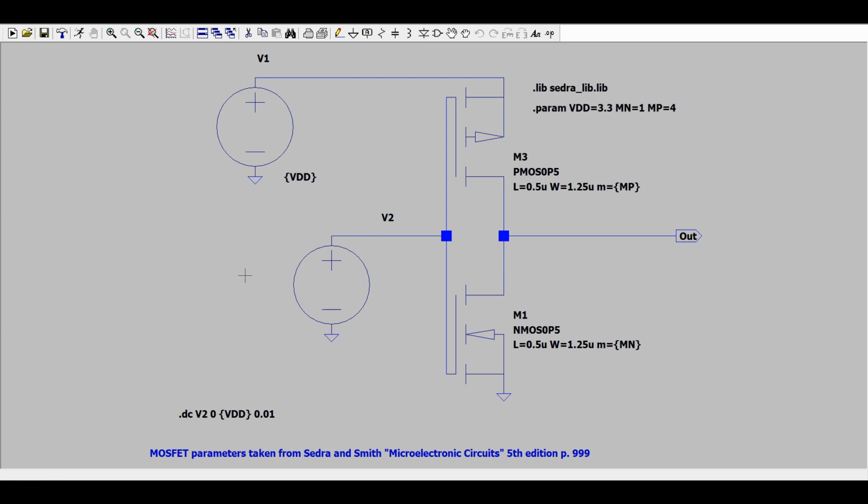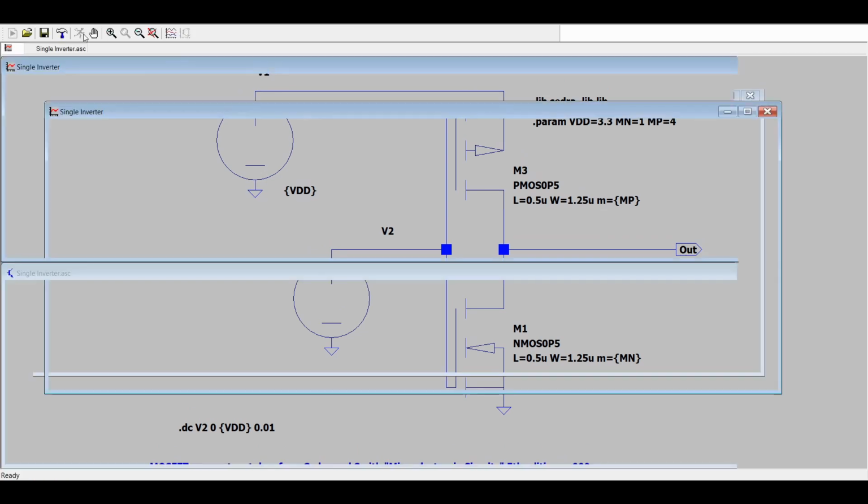But firstly, the input can't magically jump from 0 to 3.3 volts. It has to transition through all the other voltages first to get there. And also, 0 volts would imply that there's absolutely no noise, no corruption, our circuit's absolutely perfect, and that's not true in practice. So it's important to, at some stage in this course, ask the question, what happens if I put an actual analog waveform into my inverter? What do I get out? And we can find out by running our simulation.